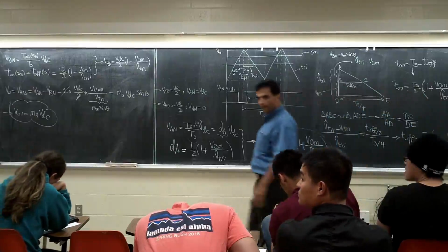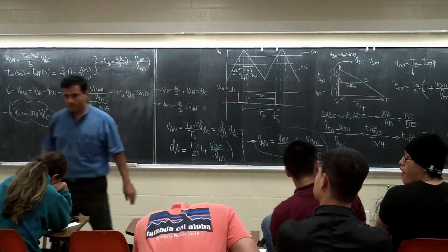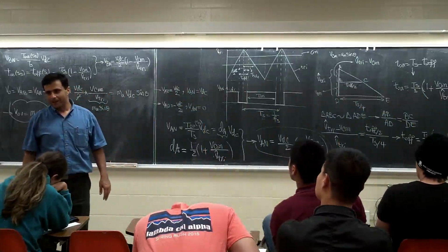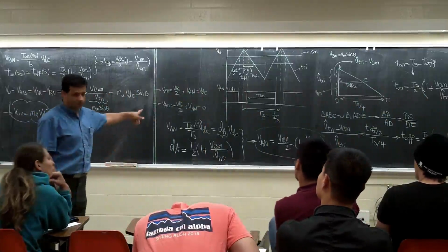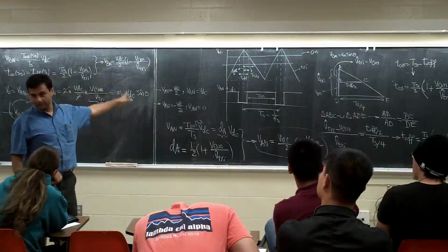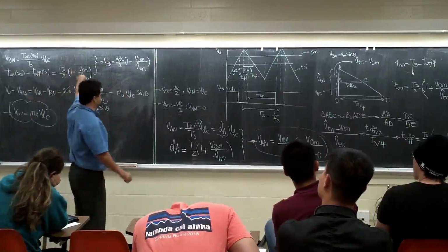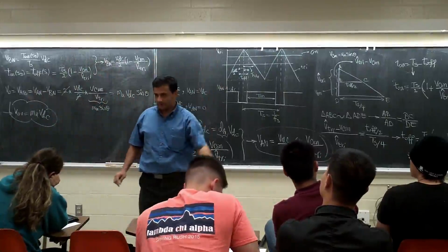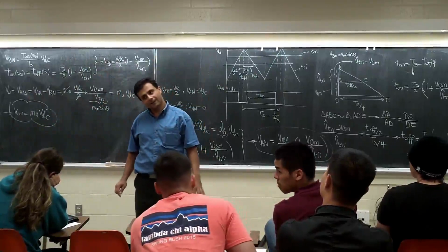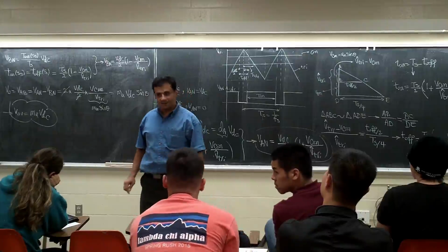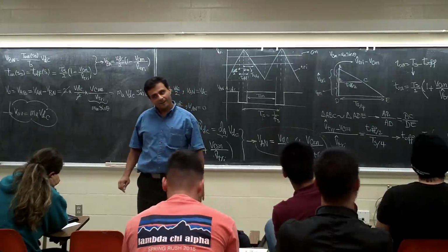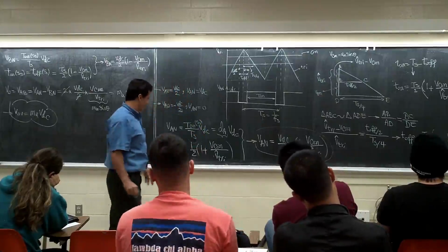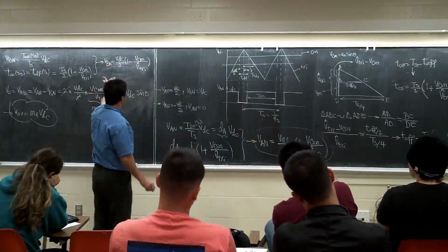How come for this we can use the VAN for the half bridge in our full bridge calculation? No, see, the reason was I didn't change my control, right? The waveform I had here, the triangular and the control, I said this is the one I'm using for leg A, right? Yeah, but in that circuit, wouldn't VAN be VDC instead of VDC over 2? Like wouldn't that equation be VDC instead of VDC over 2? No, it's going to be, I did it there.